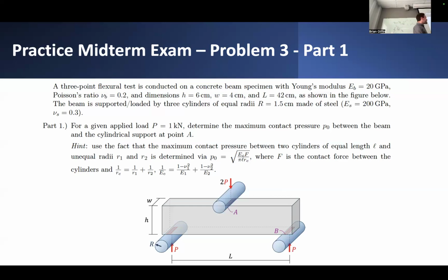Yeah. So we applied this Hertzian contact idealization to come up with the distribution of pressure that results between contacting interfaces. We covered a couple of different instances of sphere-on-sphere contact. In that situation, the resulting contact area was a circle. So between two spheres that come into contact, the contact area is circular, and we can determine the maximum contact pressure as the point at which the bubble of contact stress over this circular patch of area achieves a maximum.